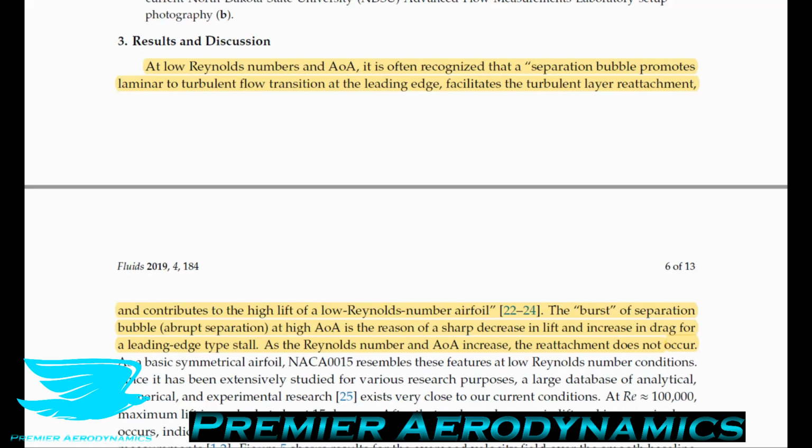So this is quite a dense part of the paper, it seems, where there's quite a few different parts to talk about. So leading edge stall, let's talk about that a little bit. Depending on how thick your airfoil is, you're going to have different stall patterns. If you have a very thin airfoil, like a NACA double, let's say it's 2% or 3% or whatever, then you're going to have stall starting from the leading edge, and the entire airfoil is going to be separated very quickly. So it's almost like instantaneous when you push it to a certain angle of attack. As the airfoil's thickness increases, this stall starts at the trailing edge and it moves up. So it's a more gradual stall.